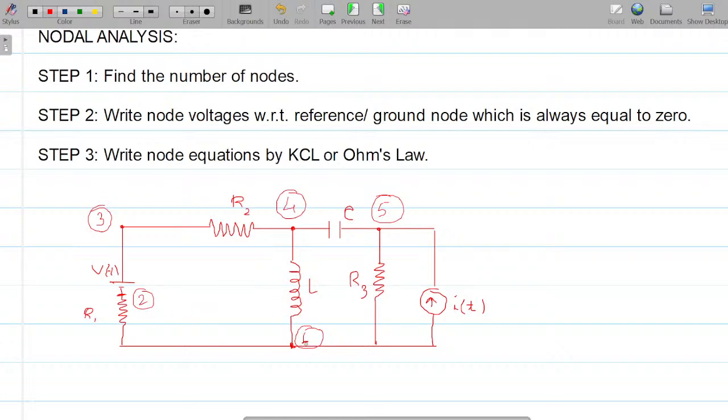So starting with the ground potential, you see three interconnections, you will mark it as a node. Move on, you encounter a resistance, it is bound to make a change in the potential, you will mark it as node 2. Now you encounter another element, this is your voltage source, you'll mark it as 3, 4 and 5 and so on.